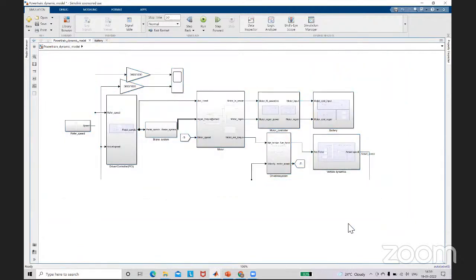And in terms of the dynamic approach, it is very easy to understand the performance analysis of your vehicle and also the sizing, and it will be very accurate compared to the quadratic approach, based on the available powers. By assigning the available powers, you can deal with the requirements in terms of motor torque, speed, or the battery sizing requirements.